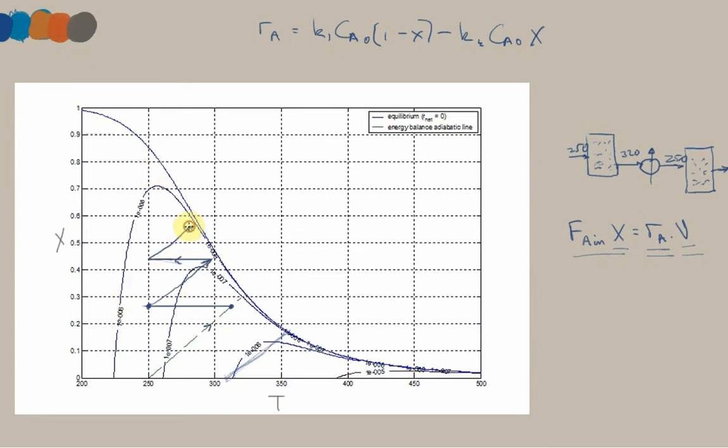Of course, we should bear in mind the expenses involved. So cooling to this degree, cooling all the way to 250 Kelvin, that's pretty expensive. And each new line here is a new reactor. So we have to consider the costs of constructing all this and weigh that against the benefit of achieving a higher conversion.